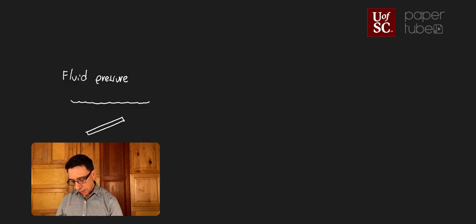What we're going to see is that the pressure at this point over here, when you don't have as much depth, is going to be less than the pressure at this point over here, when you have more depth in the water. Of course, there's going to be a pressure on the other side of the plate, but for now, let's just look at the pressure on this side of the plate. So we'll have a value of pressure over here, and that's going to start increasing to a larger amount over here, right? So something like this. And then that is going to form our distributed force.